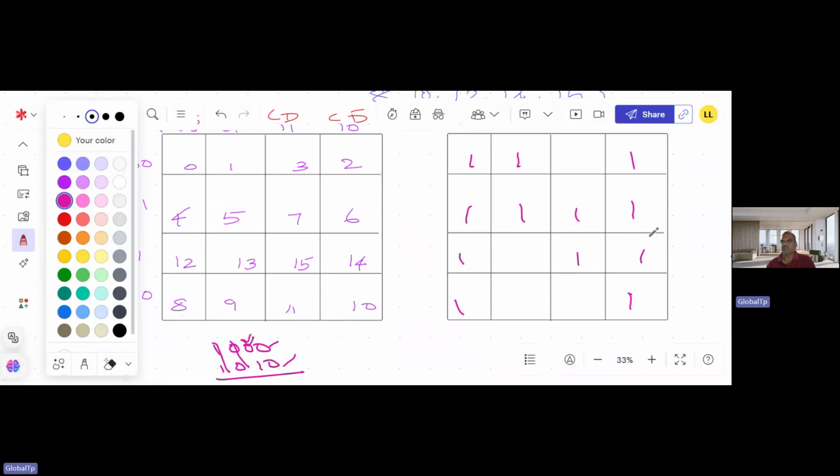As per a Karnaugh map, each and every variable which you are combining should vary by only one position. If they are varying in 2 positions or 3 positions, you should not combine. So as per this, 8 and 10, 12 and 14, 4 and 6, 0 and 2, you can compare individually. It will vary by only one position.